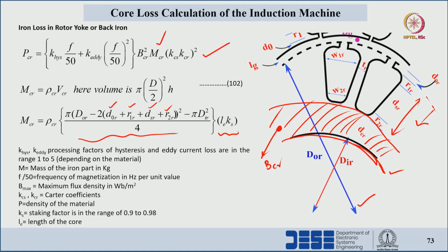With this I am concluding. We have discussed the stator copper loss and rotor copper loss, and how to calculate the core loss with different methods. Method 1, we can directly take the power loss in terms of watt per kg, multiply with mass, then we will get the core loss directly. Method 2, by utilizing the equations in terms of hysteresis coefficient and eddy current coefficients and mass of the different parts of iron, etc. Thank you.